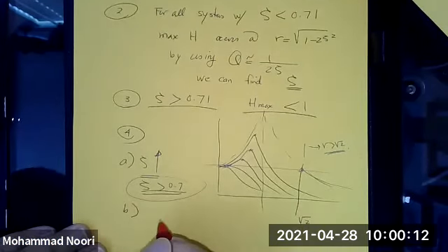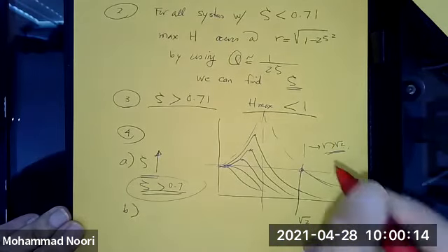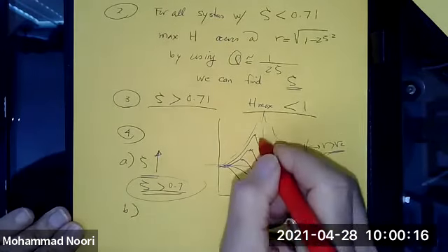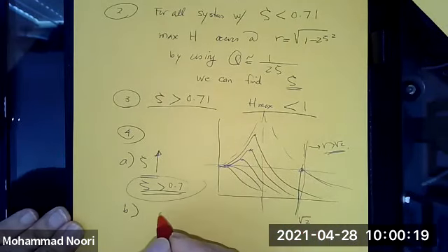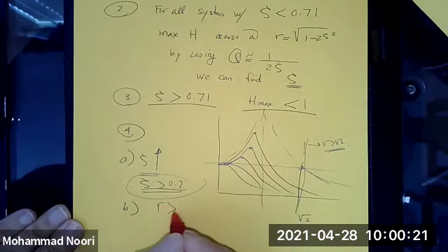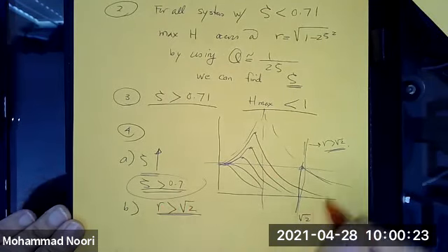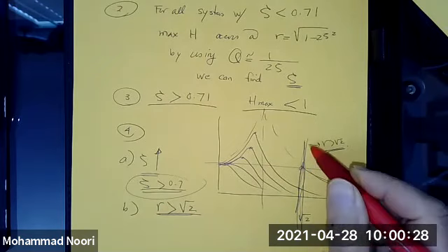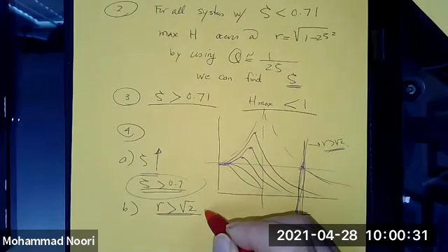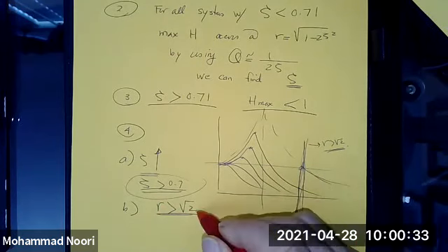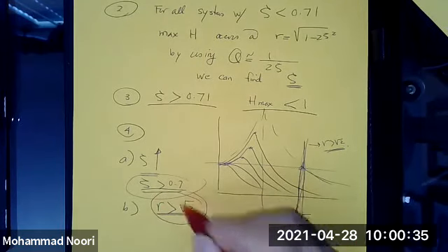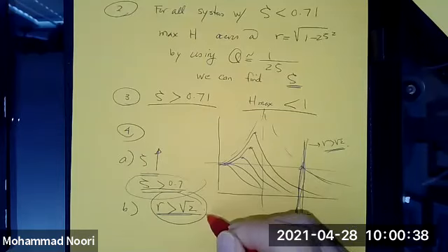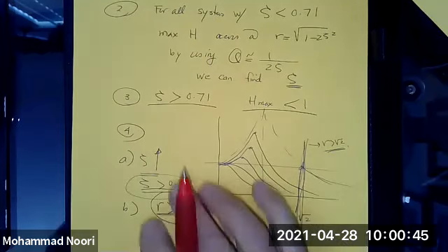But we can also say that when the frequency ratio is greater than square root of 2, we are guaranteed that the dynamic displacement is less than the corresponding static displacement. So this frequency ratio has a significance. So bear these in mind.